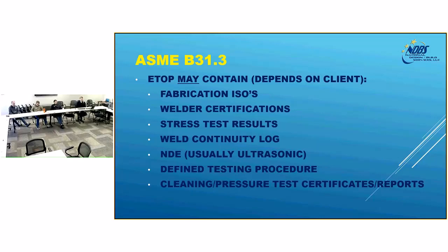And we touched on this in a different session, but the delivery execution strategy for manufacturing work, pharmaceutical work, is different than it is for commercial work, which is B31.9 for the most part. So fabrication ISOs may or may not be part of the equation, but clients may require them. So it's a good question to ask if you're bidding any of these types of systems.